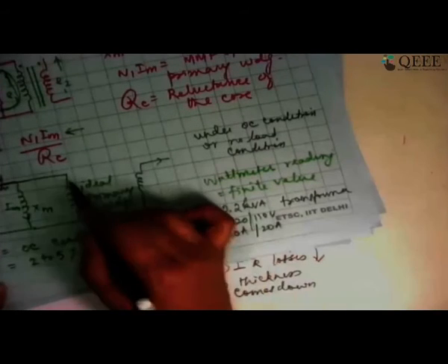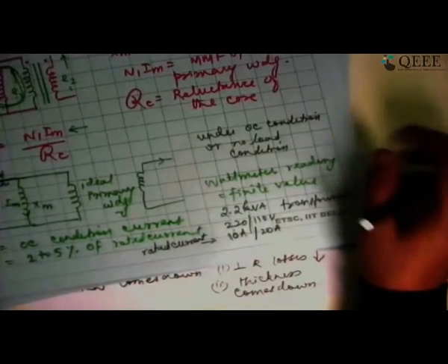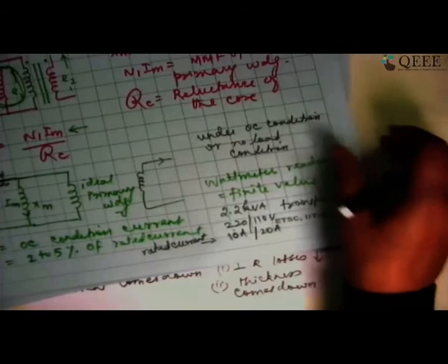So because the current is so small, there is hardly any resistance loss in the primary winding as well as secondary winding. It is going to be really, really small. So hopefully the entire loss takes place only in the core. So we call that core losses. So let us try to expand a little bit upon what are core losses or iron losses of a transformer.